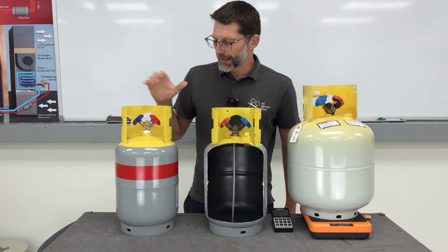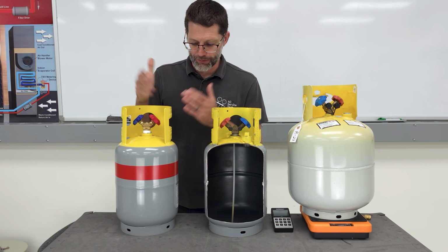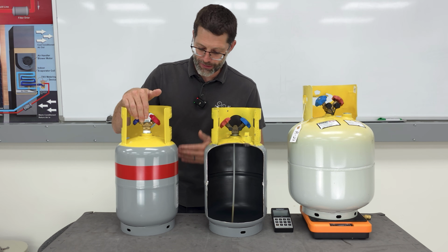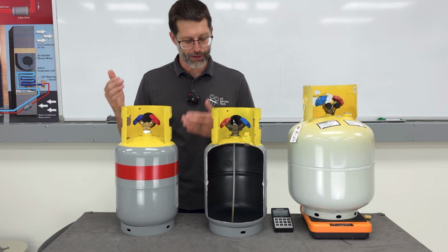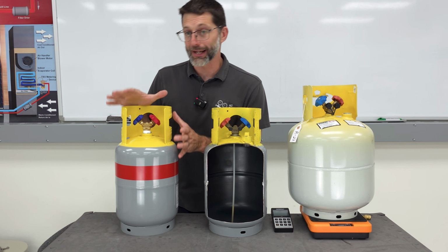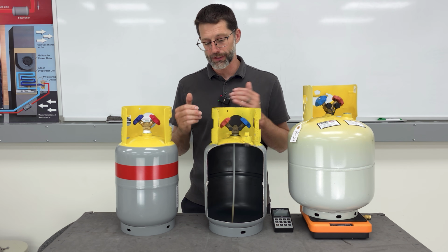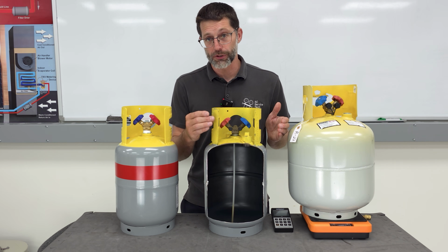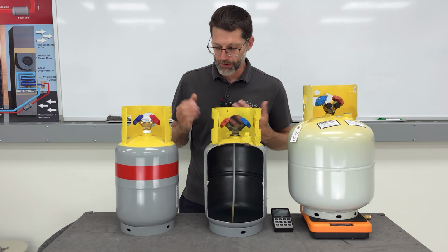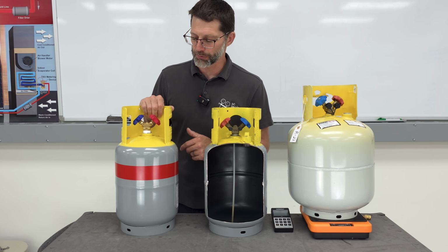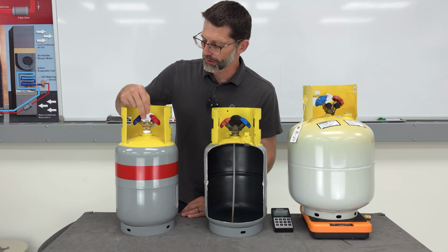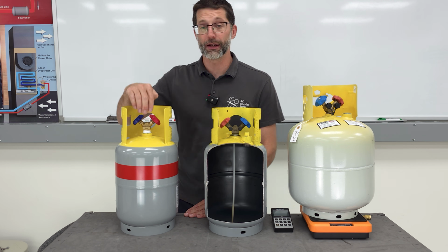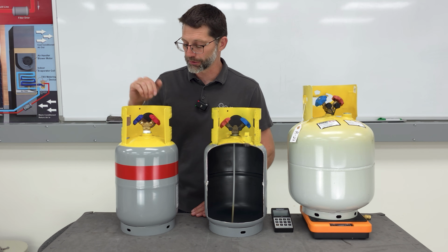And speaking of that, this bottle is specifically designed for A2L refrigerants. It has left-hand threads. It has the red stripe, but you might not be able to get your hands on these bottles right now. It just depends. So if you need to recover an A2L refrigerant, you would mark it with the type of refrigerant that you're recovering, put the red stripe on, and that's basically what you would do. But on here, you'd need a left-hand, right-hand thread adapter in order to put onto the ports right there.